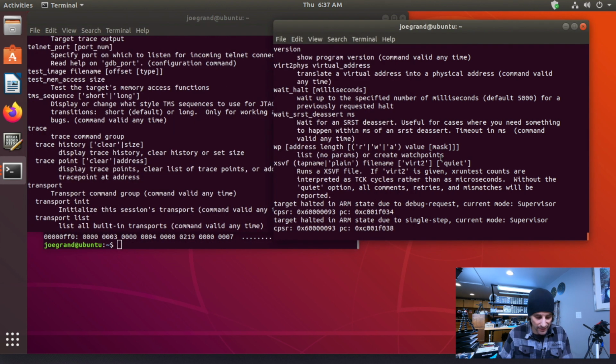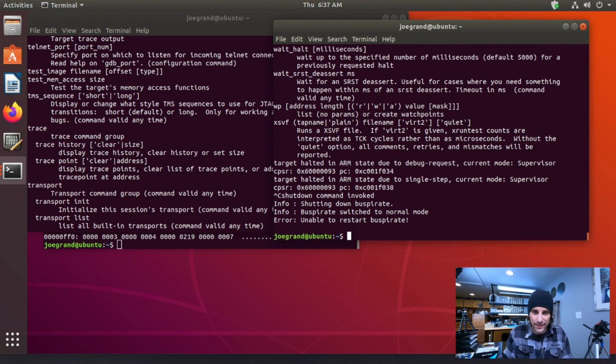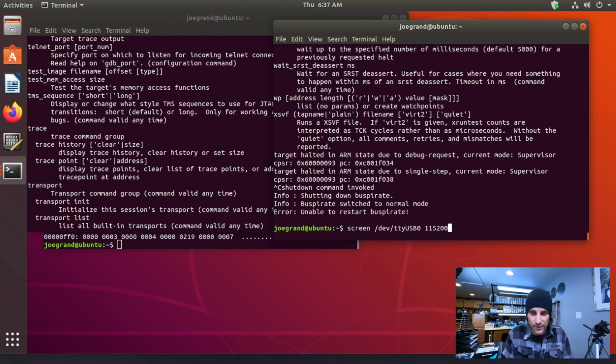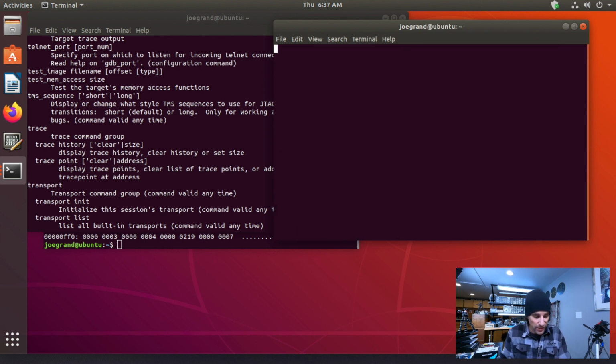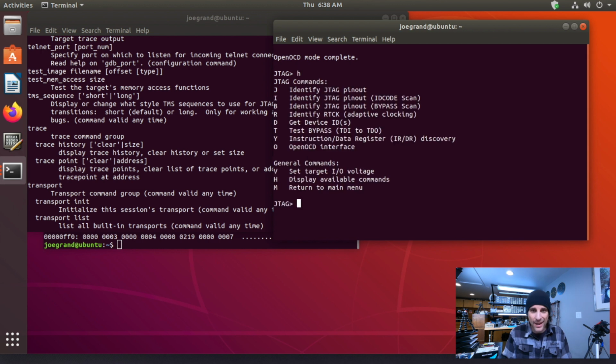And so let's just finalize this. We'll exit. We're going to go back to the JTAGulator screen, hit Control X, OpenOCD mode complete, and now we're back and ready to do more stuff if we need to. So there you have it. A currently up-to-date video on the JTAGulator.